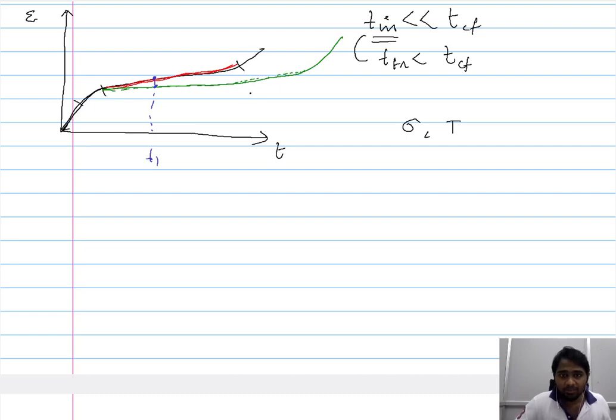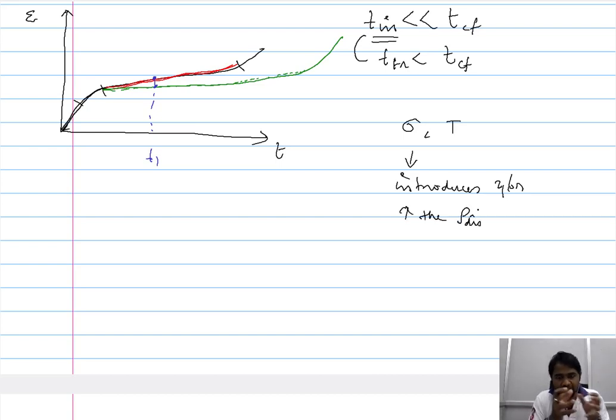In that stage, when you say that there is a plastic deformation observed, it means this stage increases the dislocation density. So in this stage, a significant amount of dislocation is introduced, significant amount of dislocation is made active, and these dislocations travel, and since there is a large number of dislocations and they interact, what you essentially observe is strain hardening in this region.